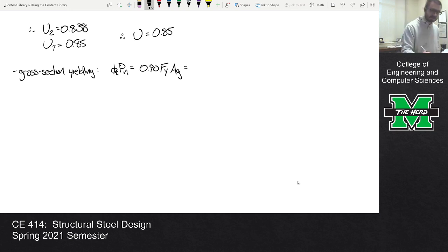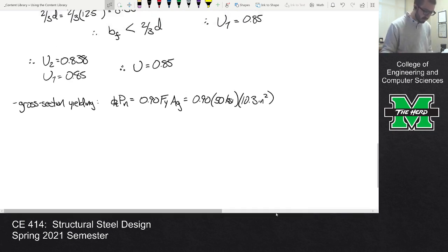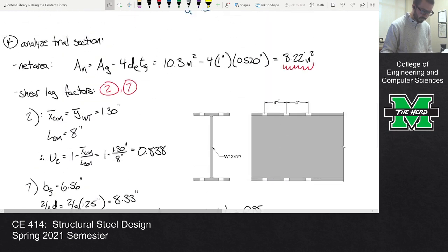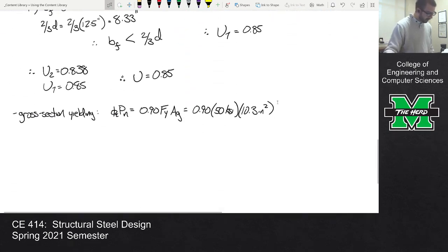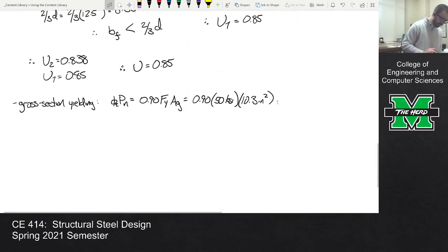FYAG, so that's 0.9 times 50 KSI times 10.3. Did I get, is that the right number? Hold on. Yeah. So 0.9 times 50 times 10.3. I'm getting 463.5. Is that correct?